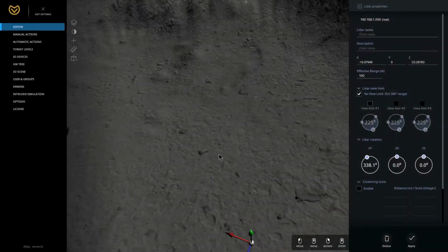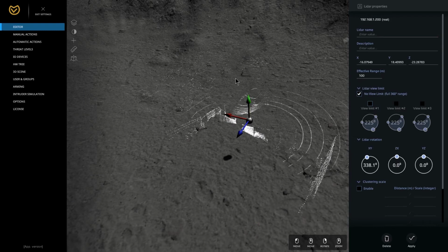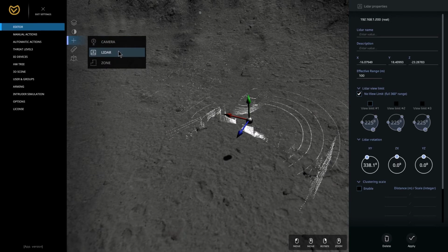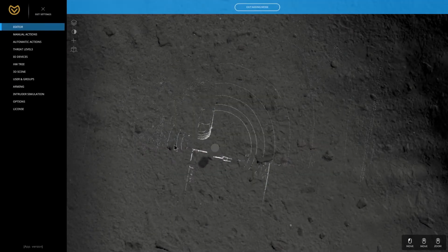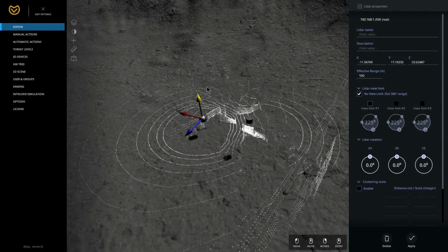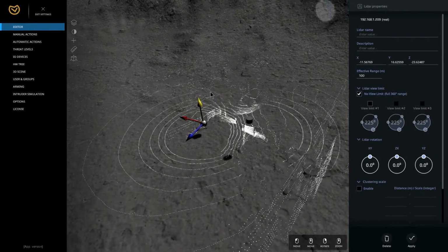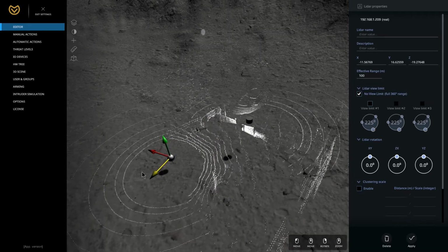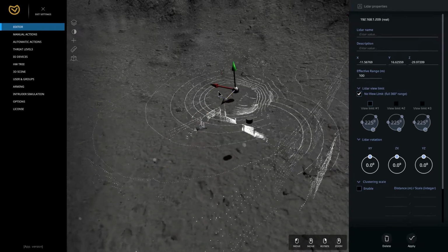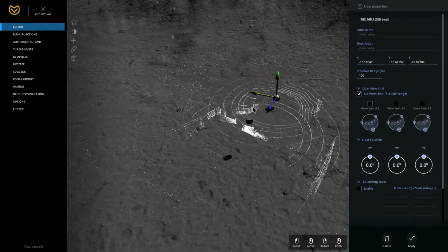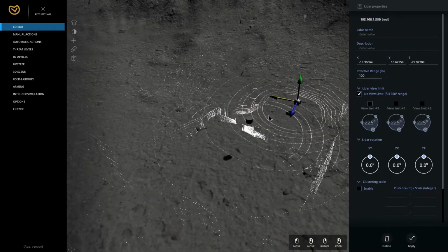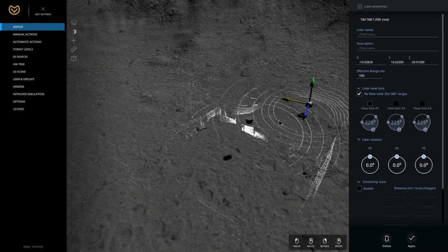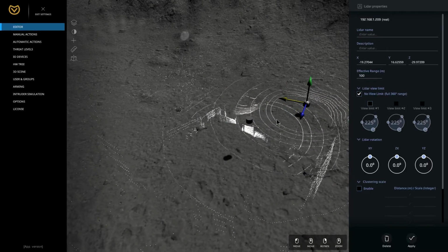There will be a time where you have more than one Lidar that you will need to calibrate. To do this, you will first need to add in the 2 Lidars. In this example, we have already added in the Lidar. Click on Editor, Add, and Lidar. Make sure that you can see all the points of the Lidar. You don't want to have any points below the map. You will again line up something that you know will match. Since these are real Lidar points, it will match something in the real environment, which you can then match in your 3D map.